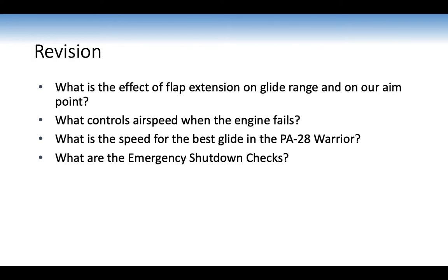But it's really important these are touch checks only. Now we've got that threat of low speed flight. The aero will be exceeding critical angle, and the undesired aircraft state will be a stall. So make sure you maintain glide.